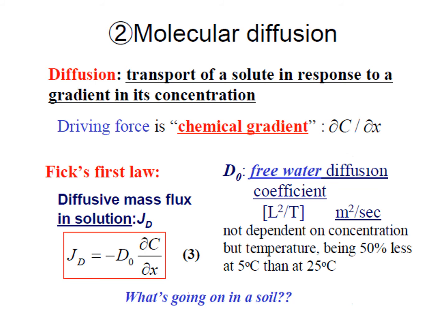So first of all, we have longitudinal and we have latitudinal movement. Similarly, the dispersion is also longitudinal as well as latitudinal dispersion. So it's all about understanding and getting the most suitable cross-sectional areas and most suitable layers, which are behaving in a similar manner, so that we can apply a similar equation for that typical cross-sectional area with the same properties. It will help in getting a simulation which is nearer to reality.